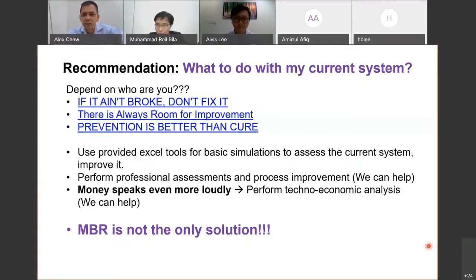Yes, I agree. Maybe I can add something on this one. Normally, the TOC depends on what type of raw waste you have. For oil and grease, I think everybody knows that above 10 ppm, oil and grease will affect the MBR. So pre-treatment before the MBR is very important, such as a chemical-physical process and aeration. For surfactants, some are biologically degradable, so they are supposed to be degraded before going to the MBR. The second case is surfactants that cannot be degraded by the microbes. Of course, we need to look into more details in order to get the right membrane to solve the problem. Hopefully, this answers your question. Okay, next.